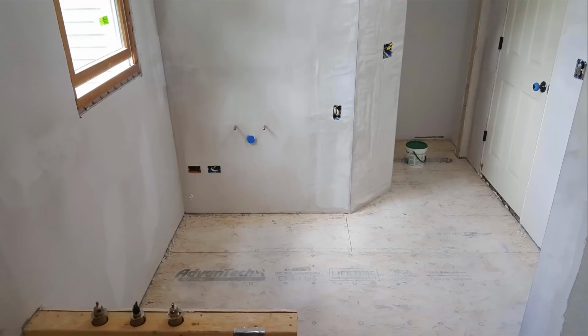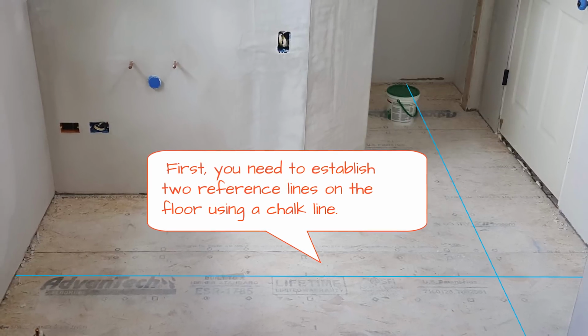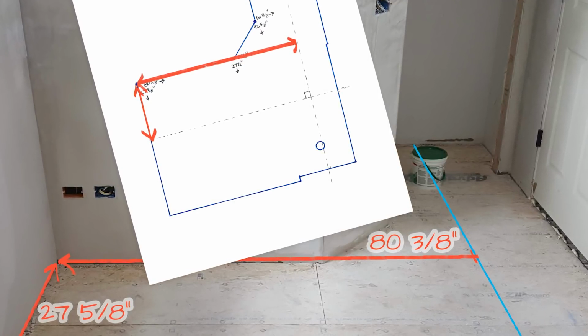Now, we want to be very accurate here. So we can't just measure the length of one wall and the length of the other wall, because the lengths of walls take no account of what angle is between those walls. So instead, we're going to create two reference lines on the floor in the bathroom, and we're going to make sure that those two lines are perfectly 90 degrees from each other. And then we'll measure from those reference lines to each corner of each wall and create a coordinate for each of those corners that we can then reproduce in SketchUp.